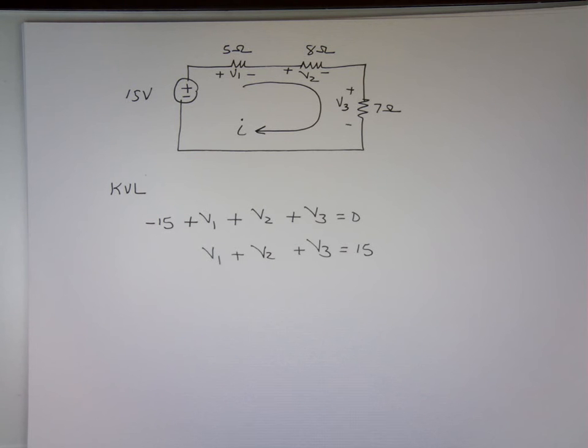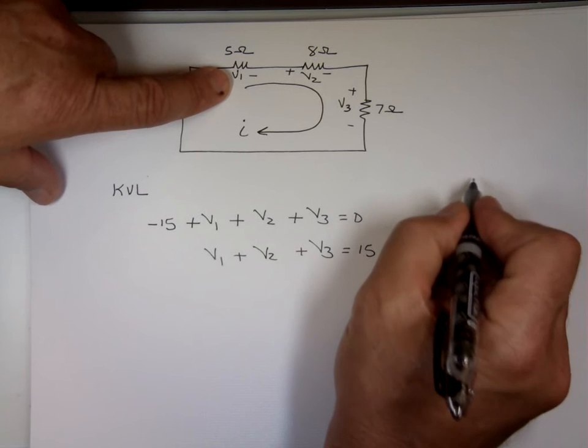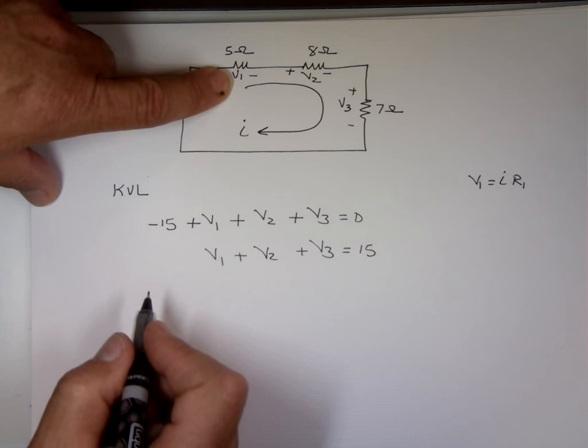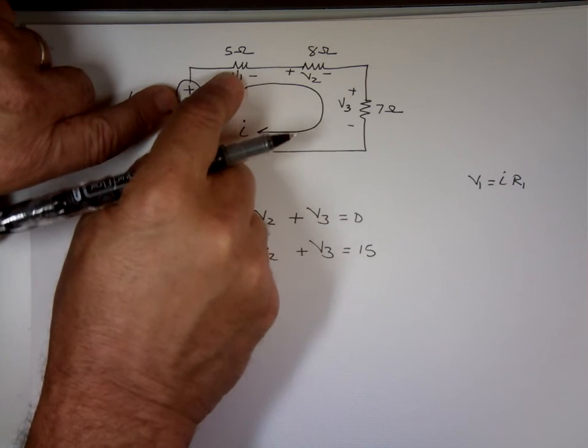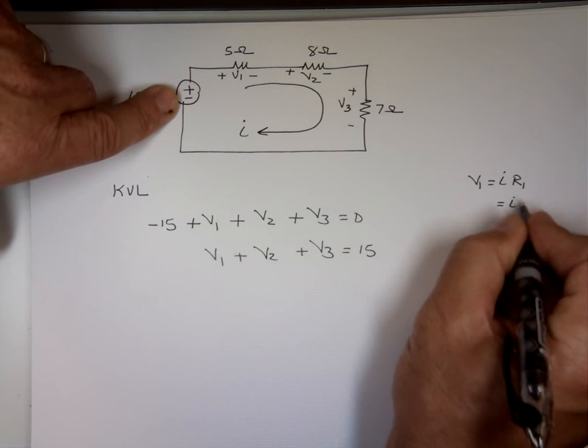Could you solve for total resistance and then get the total current? What's the total resistance? How do we know what that is? Sam? It'd be 20 ohms, I don't know. How'd you know that's 20 ohms? That's series resistors. Well, the reason you add them is correct. I'm trying to find the reason you add them when they're in series, because if you look at them, notice Ohm's law says V1 equals I times R sub 1. It's whatever this current times that resistor. Well, that resistor happens to be 5. I times 5. That's V1, which is 5I.